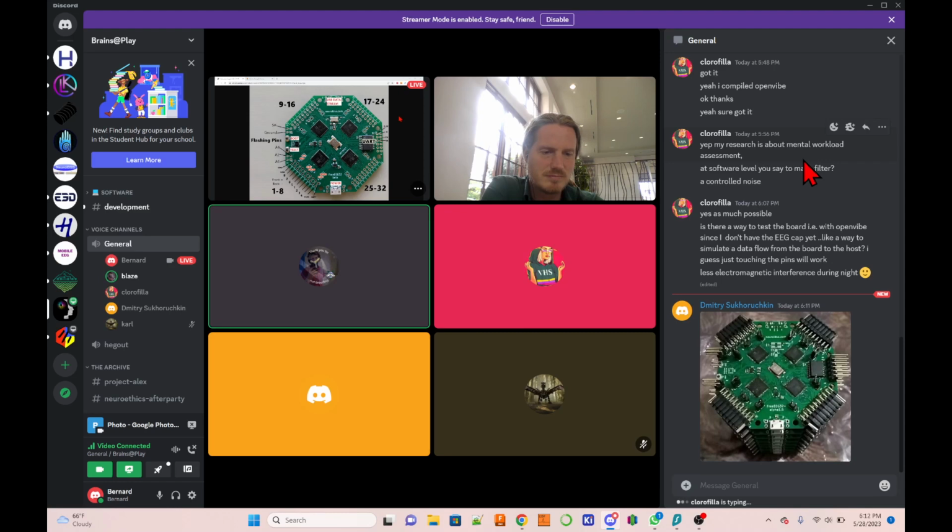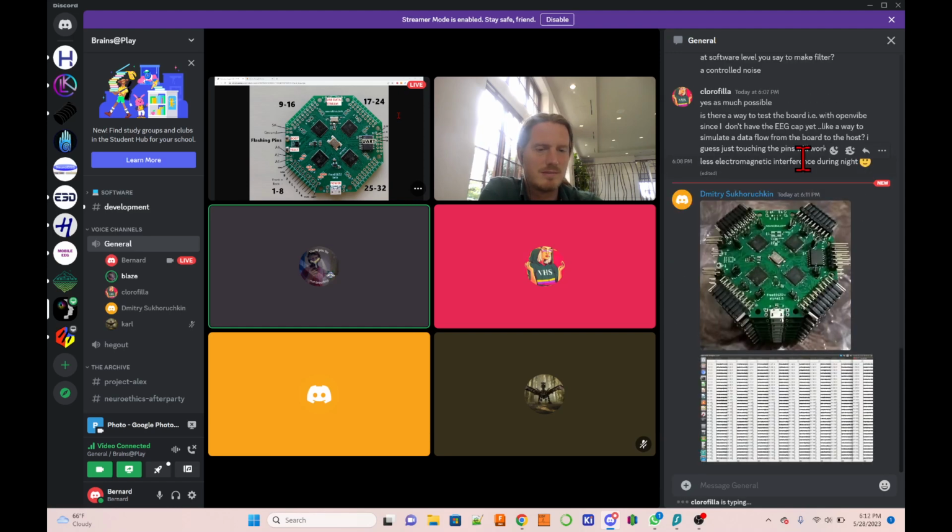I don't know if it's as useful for what you're doing, Hermesa, but I had a site that had this massive problem with artifacts, these giant noisy pulses that come along sporadically but semi-regularly, a bit like a bus: none, and then three at the same time. A friend of mine was nagging me to do it properly, and I haven't really got much stuff here. But I eventually did go to a lab and pick out a signal generator and divide that down to about 10 microvolts, and I got right to the bottom of the problem doing that, so that was quite useful.